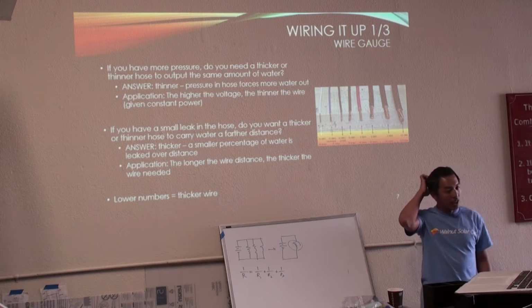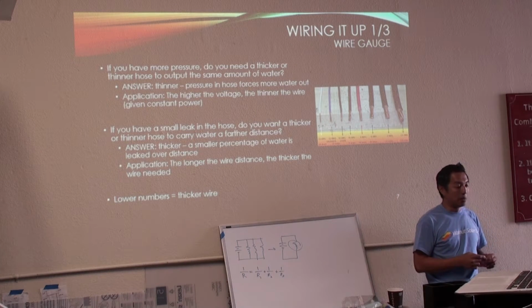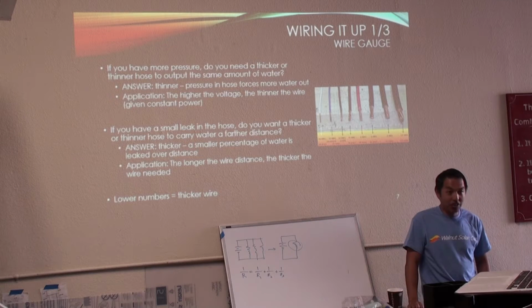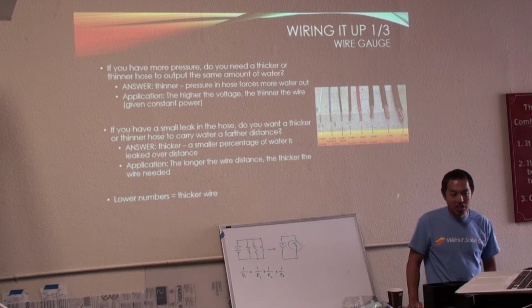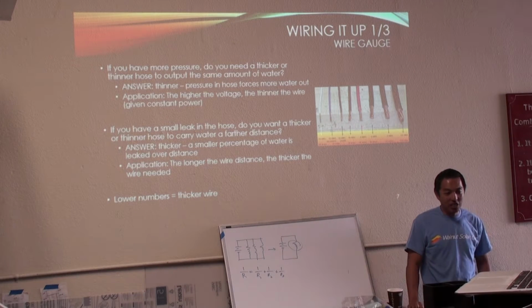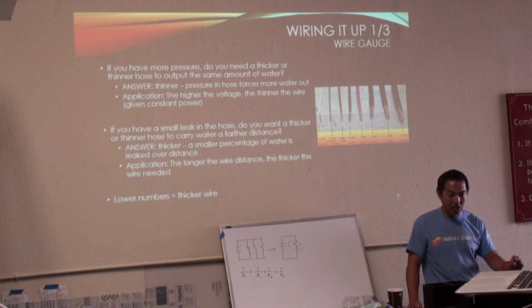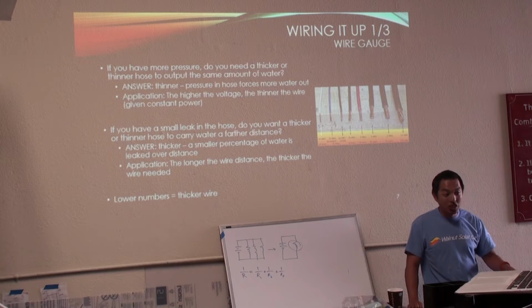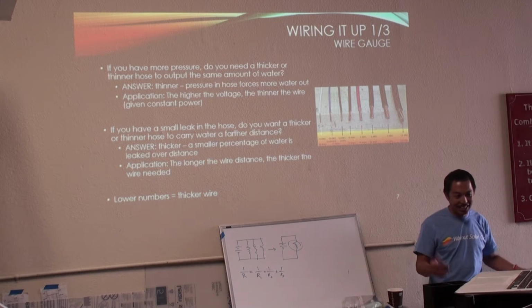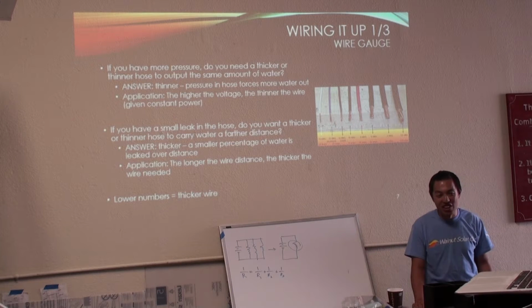Sometimes when we do solar racing, we talk about driving solar only. That's really saying whatever power I'm getting from the solar array, I'm just going to use that. I'm not going to take anything out of the battery. If we can do that, then the batteries don't discharge. We don't even have to worry about it. Or if we discharge just a small amount out of the batteries, we could get more capacity than if we just drove on battery alone.